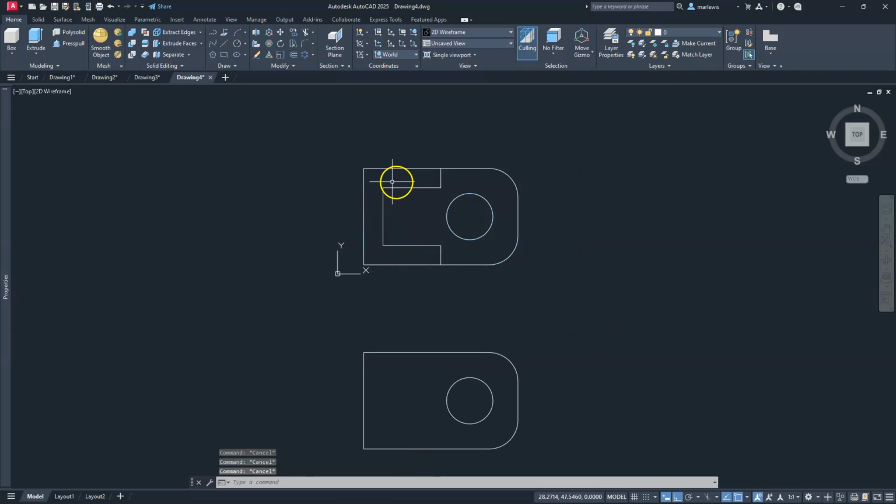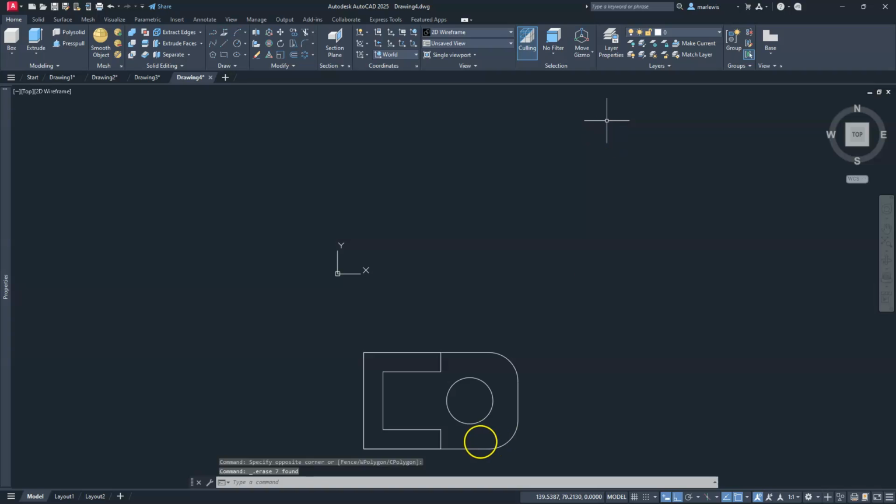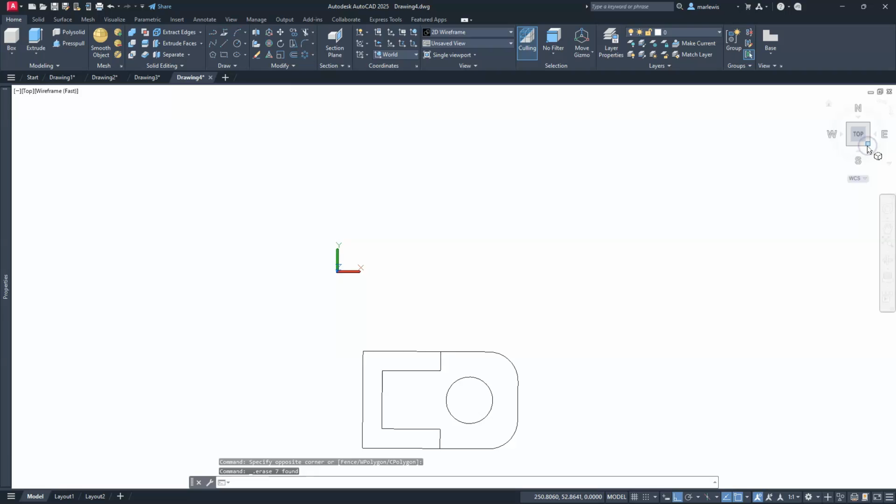This part here on the back, it needs to be a polyline, right? A closed polyline. So I'm just going to use a kind of shortcut command here called boundary. And then when the dialog appears, we're going to tell it to pick points. We will select right on the inside of here, and then we'll hit enter, and it creates our closed polyline on the inside of that. So I'll select it here. Just use the move command. I'll go from this endpoint or intersection down to that endpoint. And then this one on the top we can delete. We don't need it anymore. Okay, now let's go ahead and rotate our view to look like so.